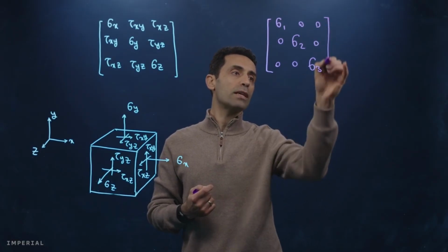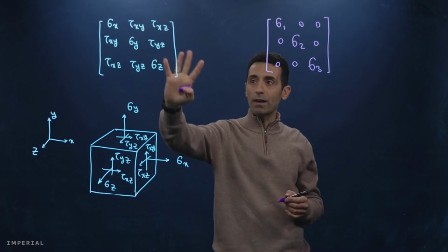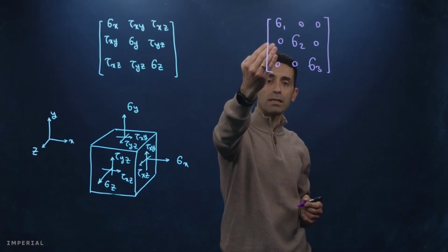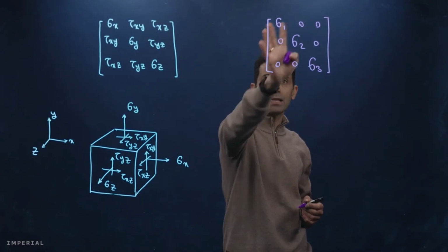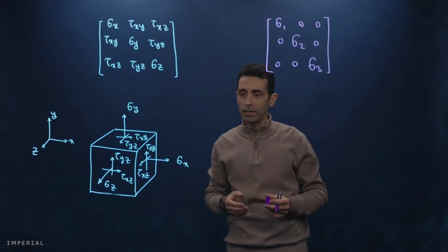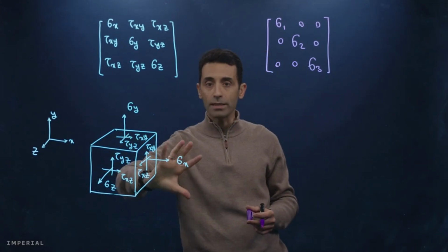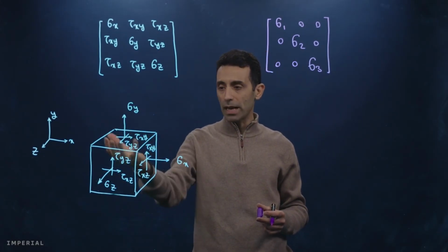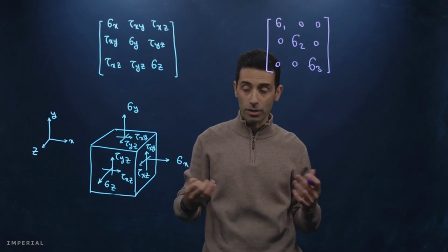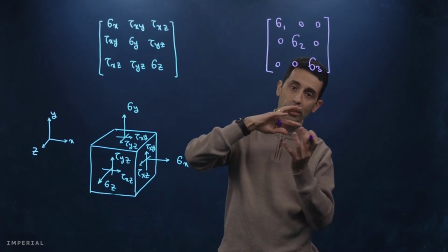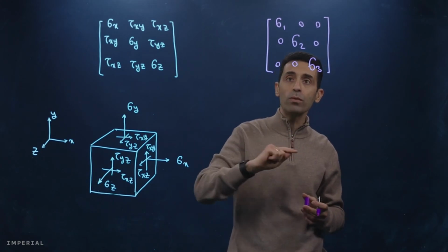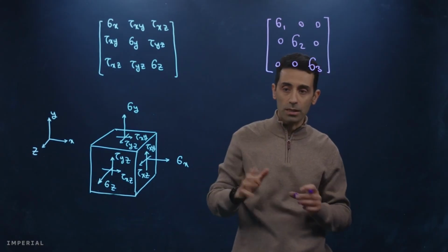I have done a transformation here, found the eigenvalues of this tensor, this matrix, and now these eigenvalues are written sigma 1, sigma 2, and sigma 3, and the rest of the components are 0. So what does that physically mean? It means that if you rotate that infinitesimal element that has the generic stress state with all 6 independent components non-zero, you can obtain an orientation for this cube, for this infinitesimal element, where you will have only the normal stresses and the shear stresses will be 0.